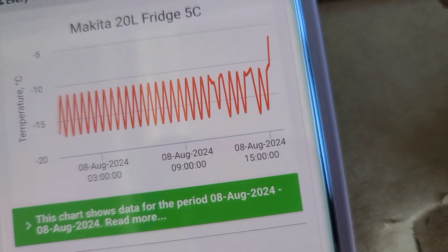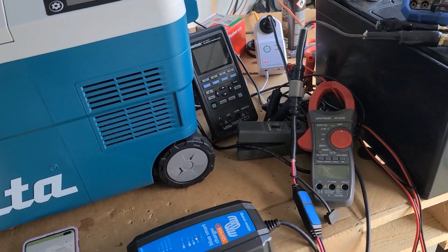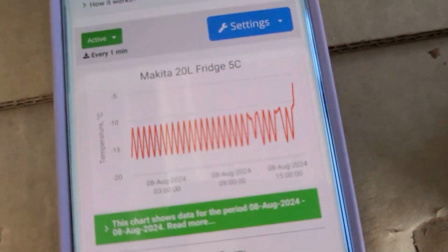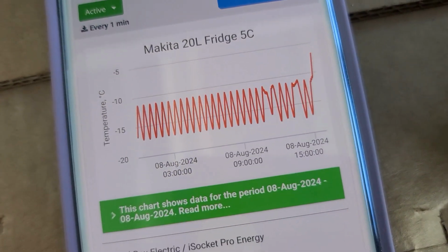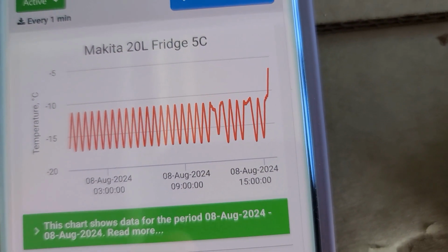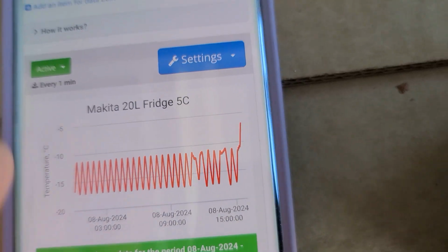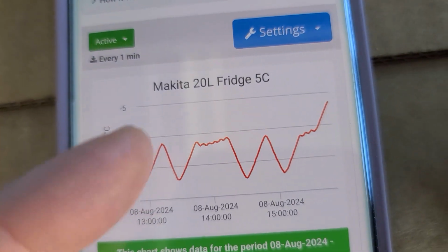So that's quite interesting, because, for example, if it would be an AC powered fridge and I see some issues here, then it is something with the compressor. It tells me that the compressor is not so well anymore, because look, profiles are always nice if the compressor is operating well and the source is okay. Yeah, really nice feature. And why is it rising? That is because I switched it off now. So there is the broken profile, you can see.